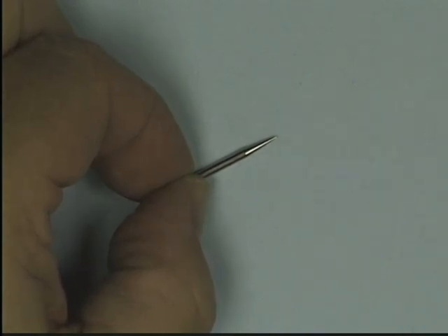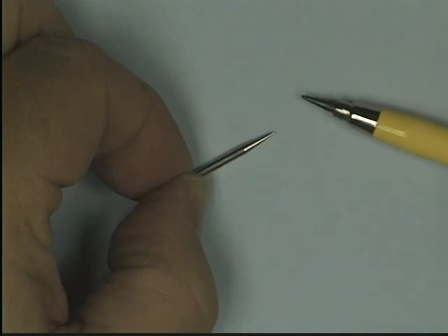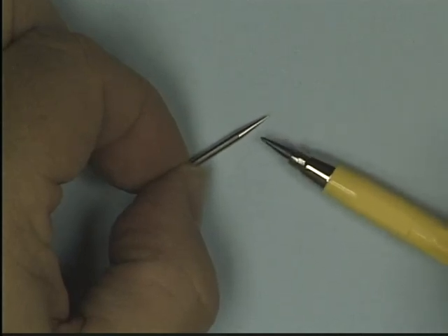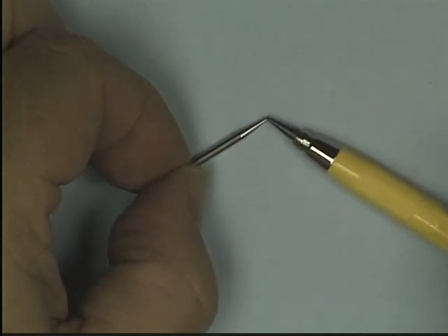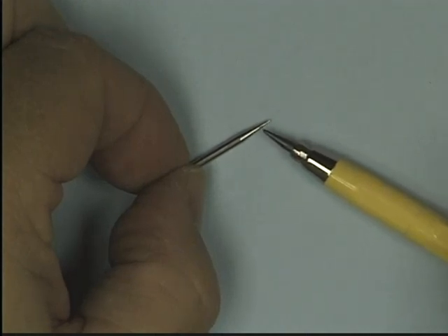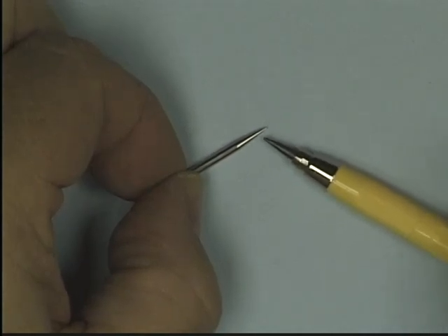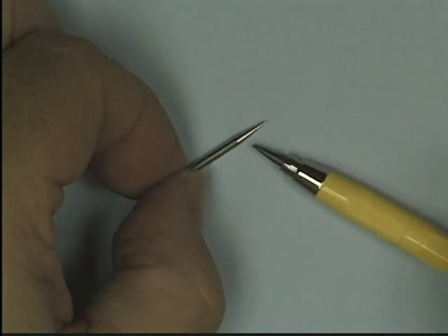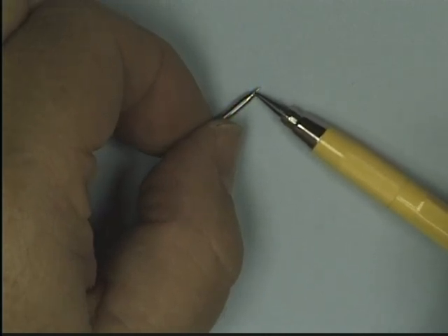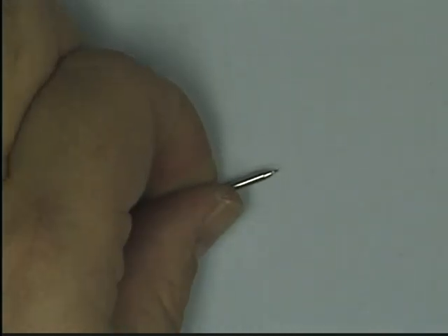We have on this drawing table something called a Borco board cover, not just a wooden surface, but a special resilient thing designed so that the compass point can stick in. And in that kind of drawing situation, I would not use the conical point compass, because if I'm making a lot of concentric circles, that is lots of circles that have the same center, if I kept pushing this point in harder and harder, it would keep making a bigger and bigger hole as this taper worked its way in. On the other hand, the point with the shoulder, I can only push it so far and it will stop and it will be much more precise. So that's the point I'm going to use in the compass on a proper drawing surface.